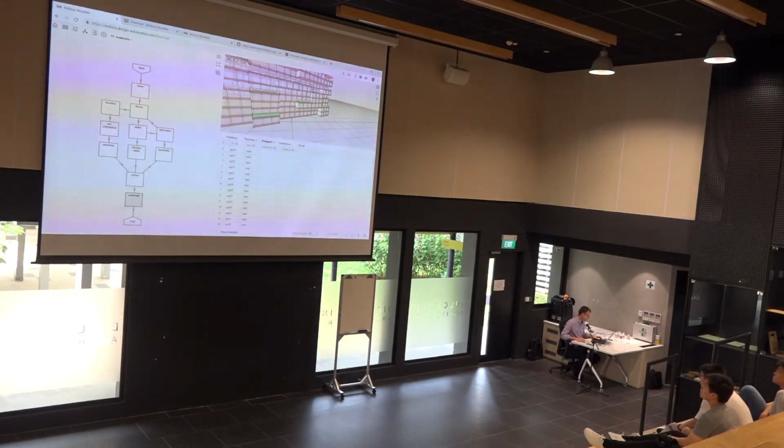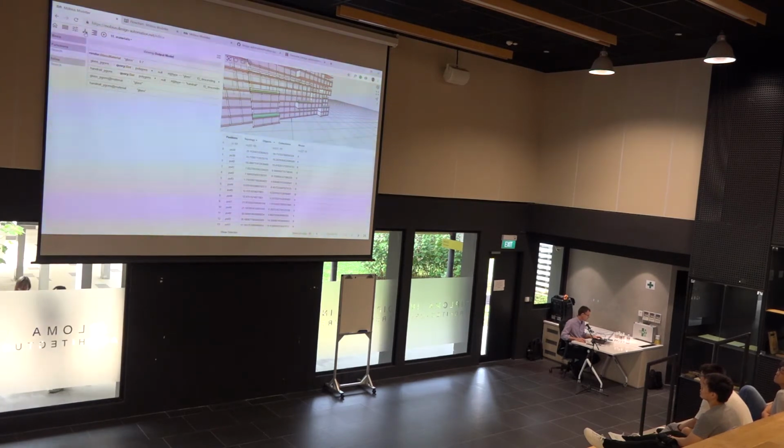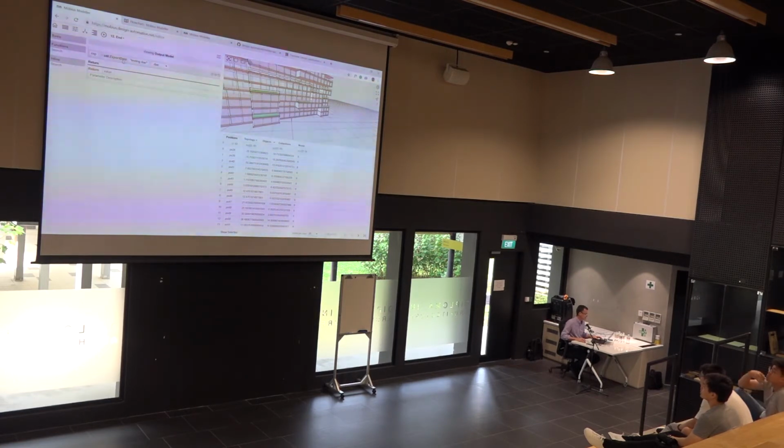So if we then import that into SketchUp, it just imports as a SketchUp model. The thing I kept cancelling is the last node here. Yes, final node here, I have export data as DAE. So DAE is the Collada file format. You can choose some different ones: GeoJSON is a geospatial format, DAE, OBJ, and GI is our own geoinformation model. So this is our own file format. And these are the other ones which you can import. So DAE is the SketchUp format, but we can import it into SketchUp and ArchiCAD.